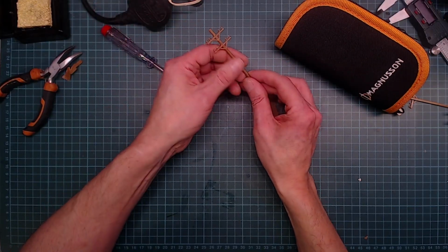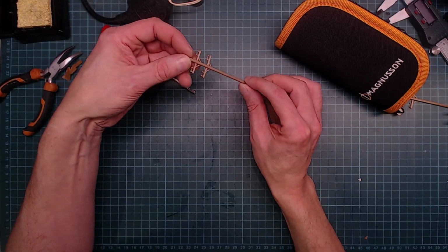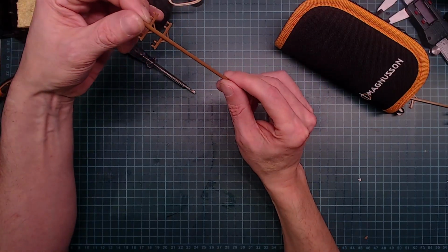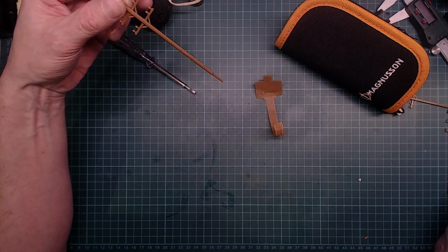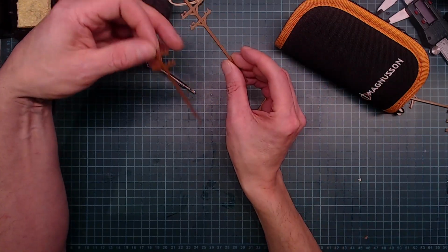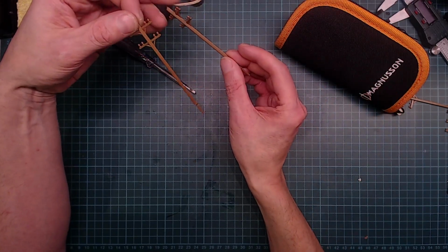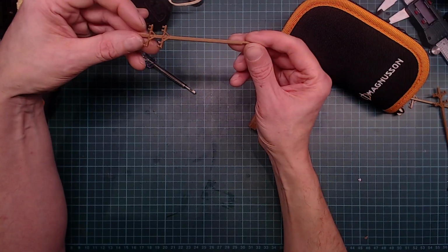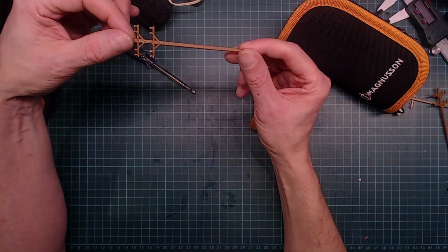It's more rounded, better detail. So yeah, use a raft if you're making these up. And this one, it's really square at the back, so use a raft when printing these flat, get more detail. Okay, back to the end of the video.